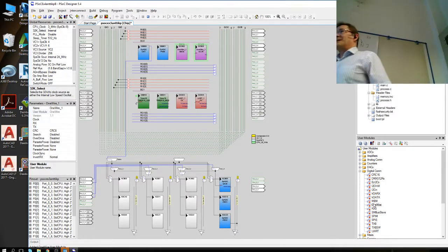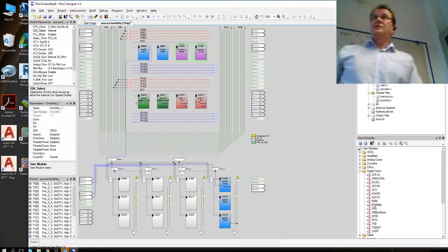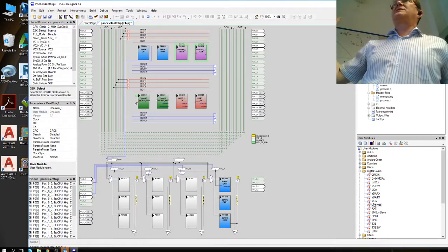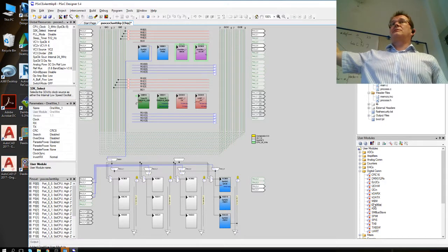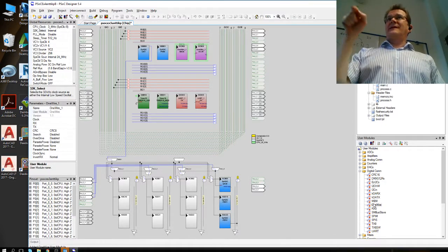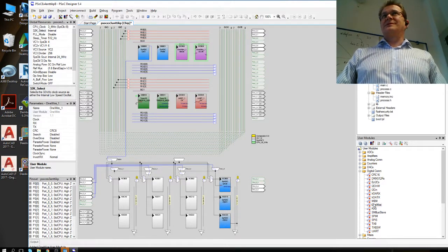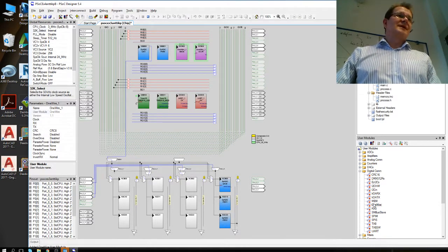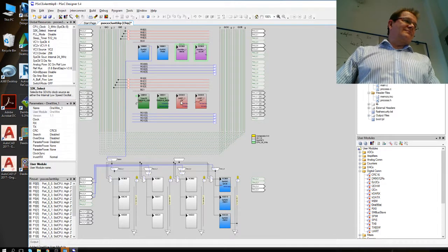If you want some more, you need to actually get rid of the one 8-bit timer there. So you would make an 8-bit timer instead of a 16-bit timer, and then have a software timer inside that 8-bit timer interrupt service routine. Yes. But now we are still lucky. We can put the UART there and the one wire block, and then we still can run the timer.